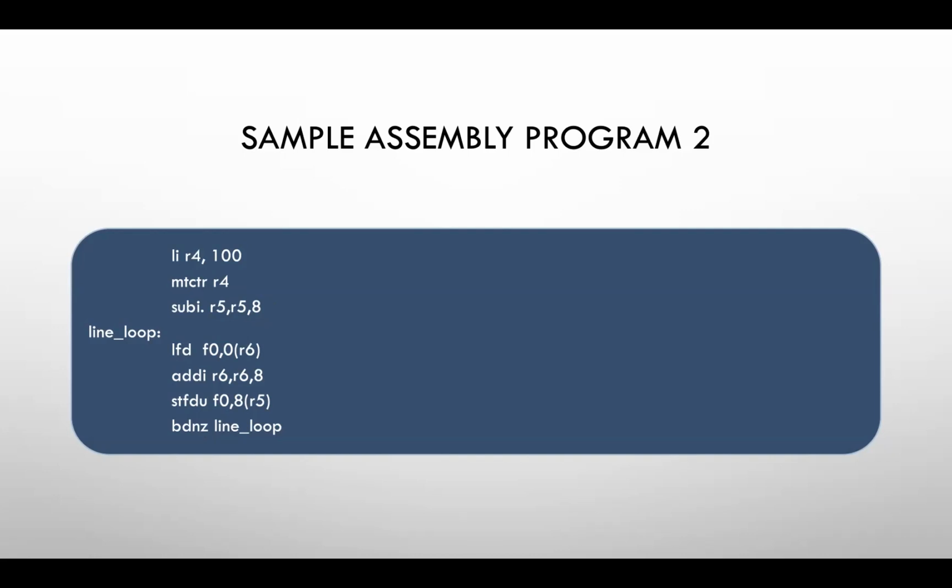So we covered in this session register conventions, and how we use those registers if we write assembly, or even if we are writing a compiler, you need to take care of this convention. And there were small sample programs which tell how general purpose registers are used, how counters are used, and how branches are used. In this branch, you are also using the count register, branch on count register. So these are all different concepts. And then the update instructions, which will update the registers and also do a load, also do a store. Okay, so these are some things I thought I'll cover in this session.